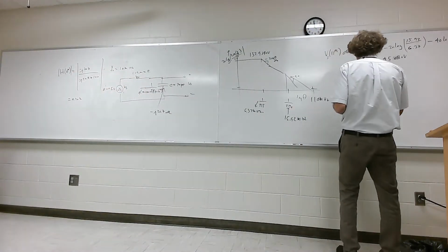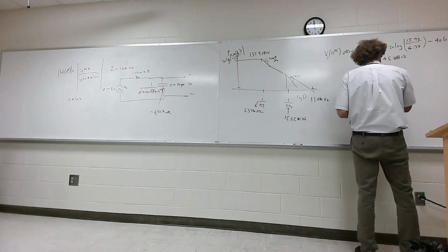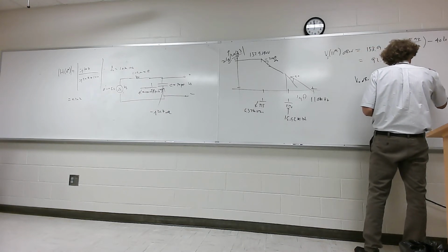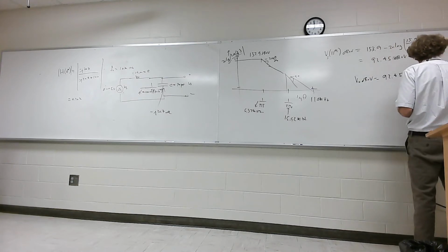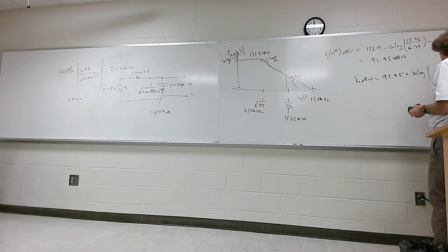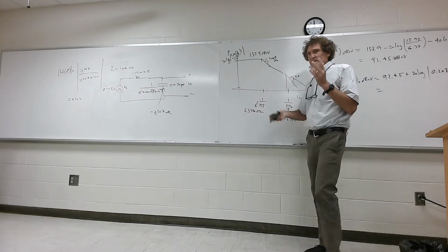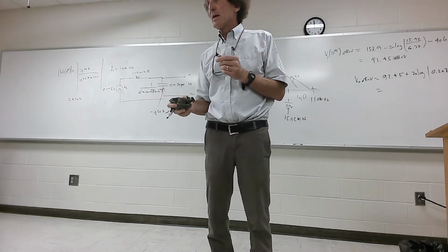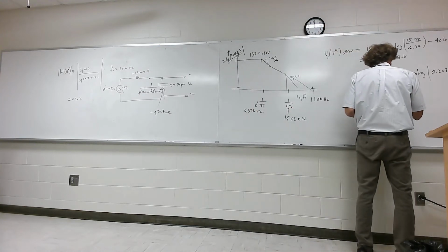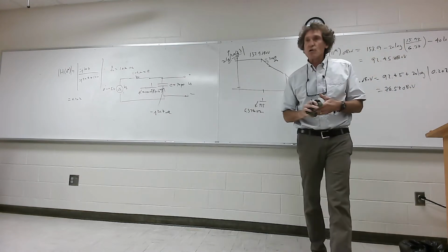So now, to get V out in dB microvolts, I take this, 92.45, plus 20 times the log. You don't have to divide this by 10 to the minus 6. The log of that, which is 0.202. And this comes out something like 78 point something dB microvolts. Can you give me it? 78.58. 78.58 dB microvolts. Now that's the worst case, the largest it could be.